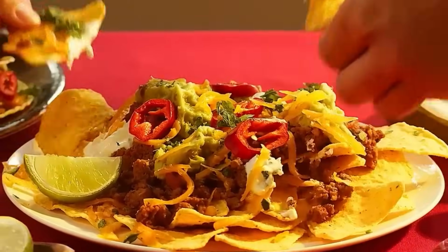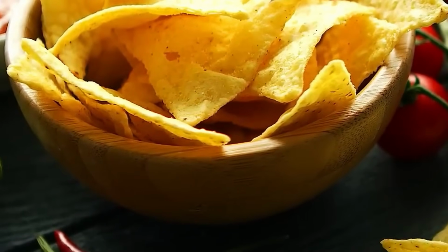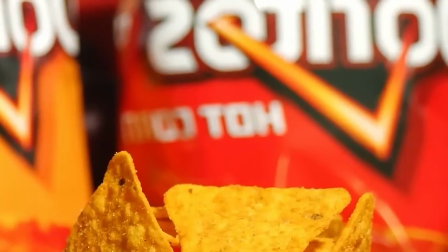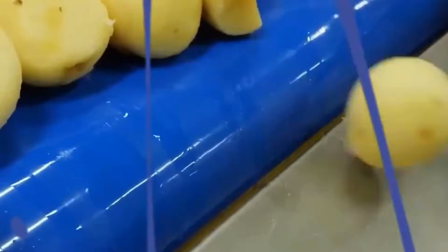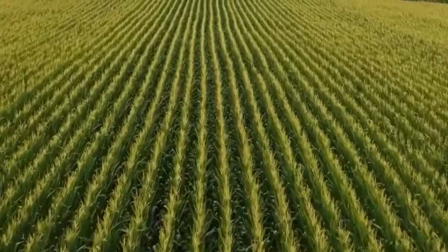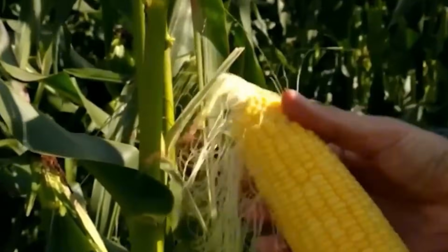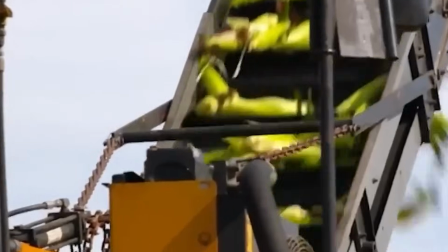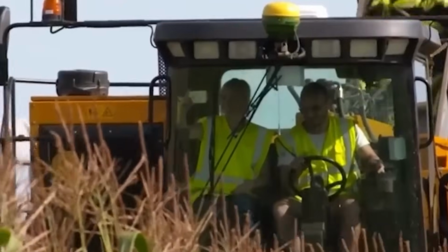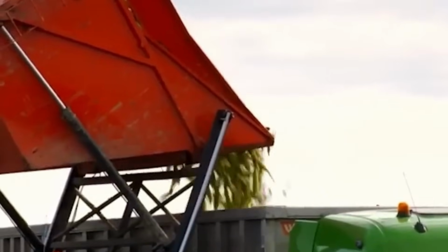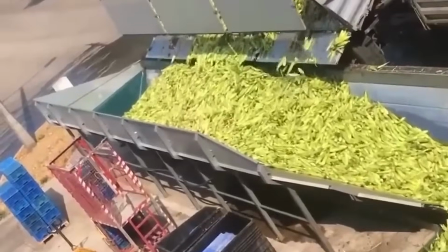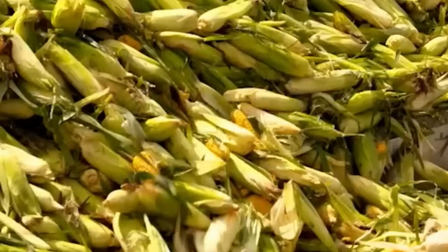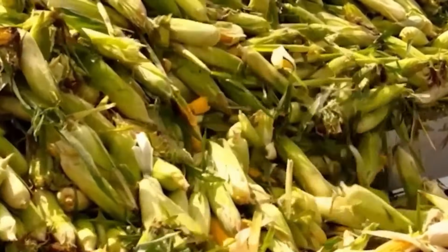expansion. Upon exiting the fryer, the chips pass through an oil removal stage. This includes air knives and optionally a centrifugal de-oiling system that rotates baskets at up to 1000 RPM to spin off residual oil. After de-oiling, the chips enter a cooling conveyor system where ambient or chilled air flows across a vibrating bed to bring product temperature below 40 degrees Celsius in under 2 minutes. The cooled chips are then routed into the seasoning drum.